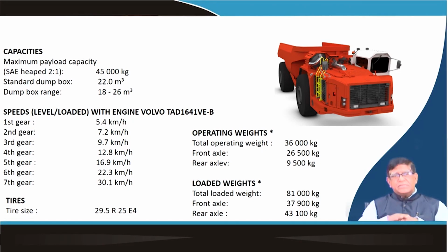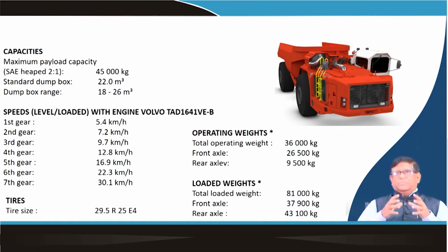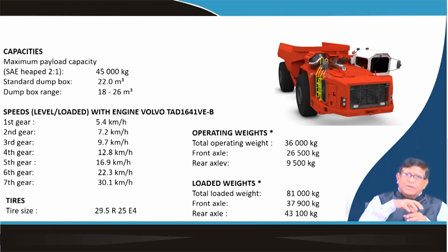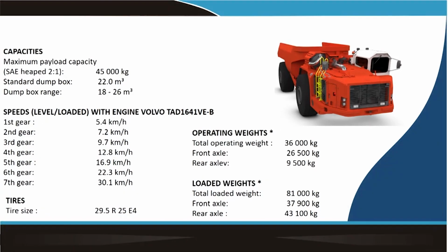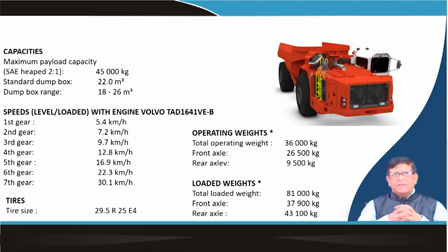Stack capacity is just like when you fill a glass full of water up to the brim. But if you put some rice or sand in a mug, you always get a heap at the top. That portion is called the heap capacity. The triangular upper portion is kept at a 2:1 ratio of slant, and when it is full, it will give 45,000 kg.